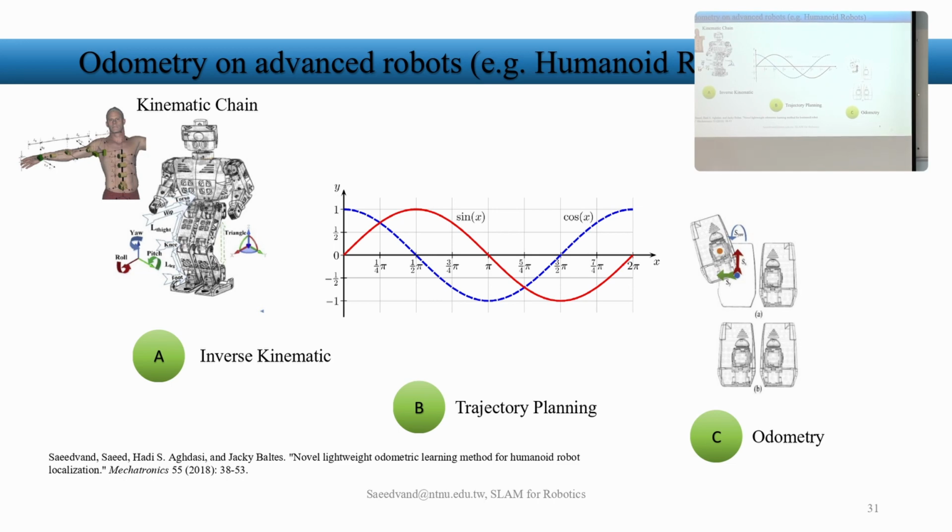That's very complex. If you want to implement it from zero yourself, you're going to suffer a lot, but it's worth a lot too. Because you implement it one time, and the next time you call that function, you say, go to x, y, z, and it calculates what the angle of each joint should be to be there. And not only x, y, z, you can have roll, pitch, yaw, the angle of the end effector, which is the heading direction of the end effector toward that object.